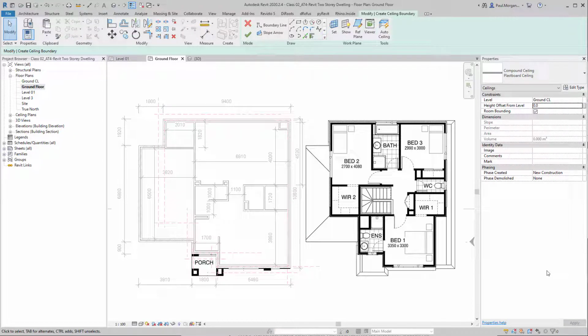You can do this. You can do that too. Either or is actually fine. Usually, the only reason why it's a good habit, I believe, to do it from the reference from the ground level is, firstly, it's easier to understand the height of the ceiling. So you can say that this ceiling's at 2.7, the next one's at 2.5 or 2.4. Sorry, the next one could be at 3.2.